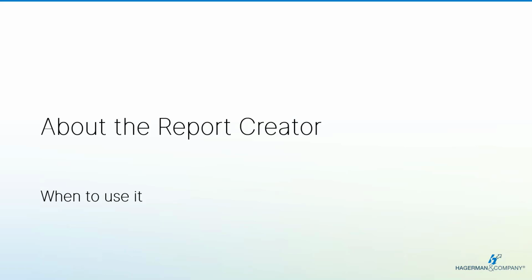which takes extra time. The report creator is the tool for generating a parts list, a bill of materials, specification sheets, using the data from your plant project, what you see in the data manager. And you can use the tool simply to run pre-configured reports in a very simple two-step process.